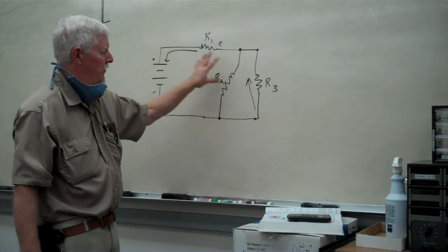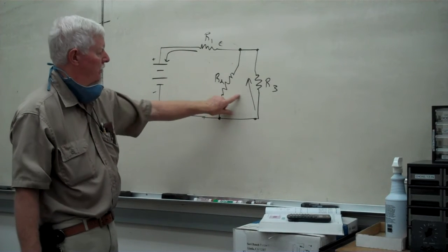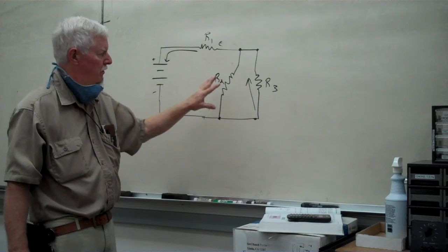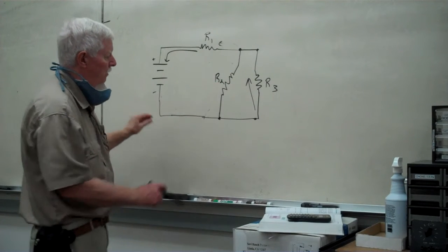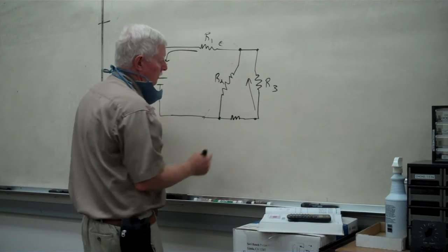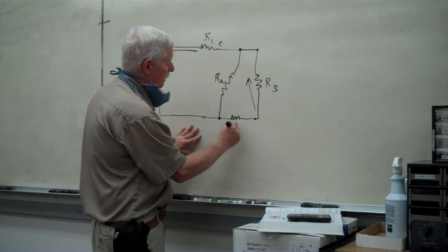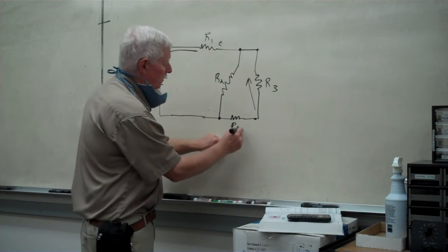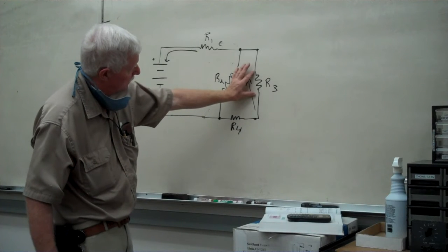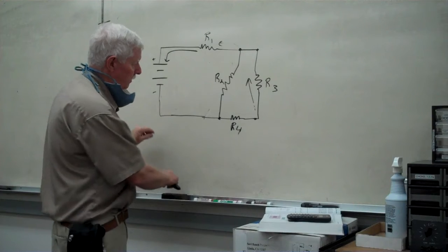The solving of the total amount of resistance for the circuit so you can find the circuit current is the same process. It's just a way of revisualizing these two devices, and if we had a third one, we could actually put a third one in here. If I were to do this, let's take this and redraw it and see what this would be if I add an R sub 4 to this entire circuit. I'm going to take this series resistor, which is in series with R3, and convert that into a single network to make it easier to visualize.